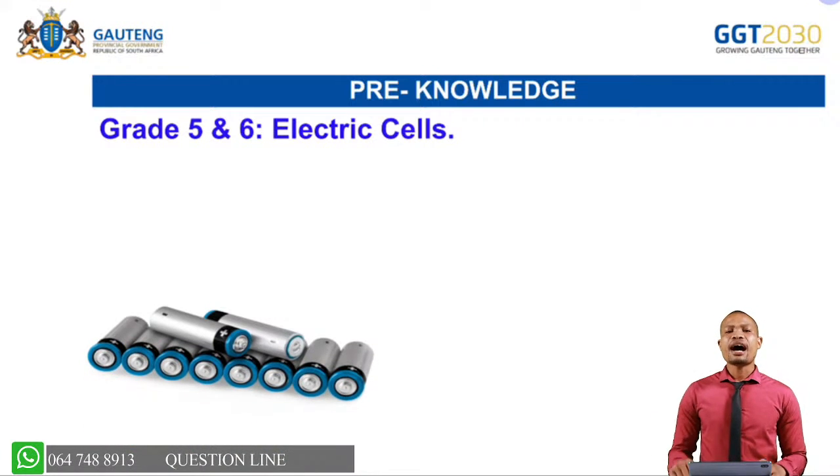Right, so these are the common cells that we normally use when we connect our circuits, either in series or parallel. These are called AA 1.5 volt cells. We can connect these ones in series or in parallel. It's very uncommon to have a circuit that connects these in parallel, but we can. When they are connected in parallel, the voltage is going to be the same as the voltage given by one cell. But when they are connected in series, we add each individual voltage to give us the total voltage.